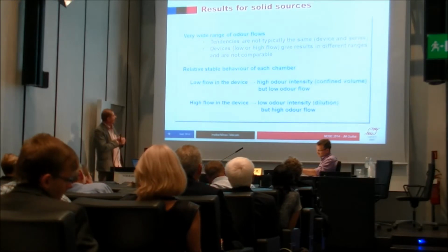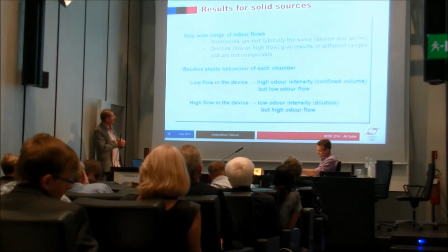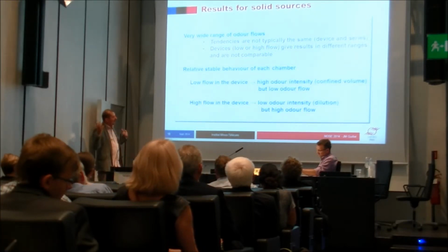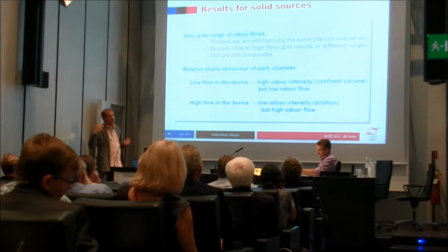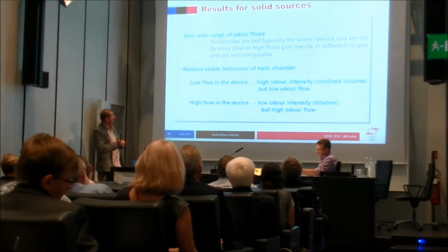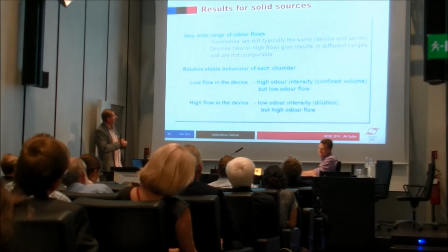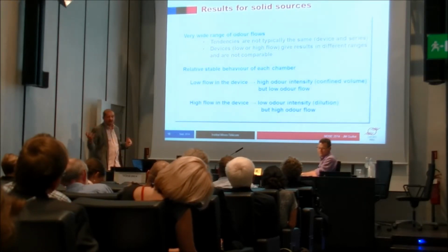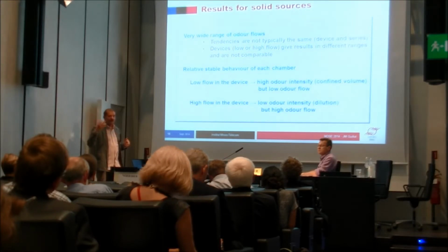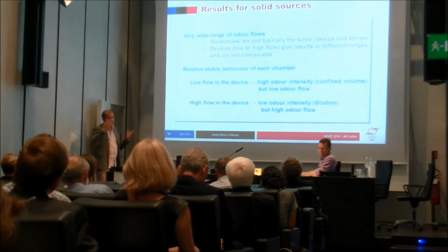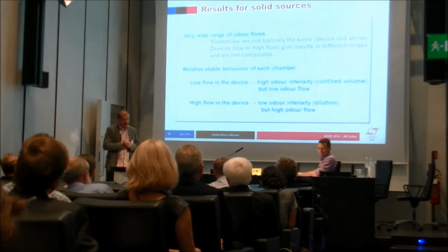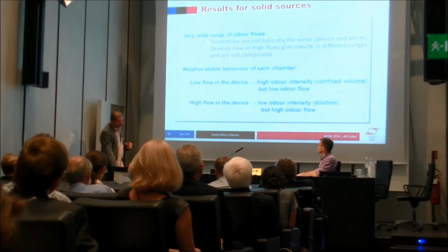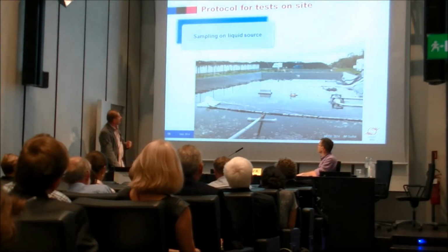And as we all know, the main problem of wind tunnels or very dynamic chambers is that you can dilute your sample a lot sometimes. But because your odor flow is a multiplication of the flow and the concentration, you can increase your odor flow to very high values in some cases. So a compromise must be chosen.